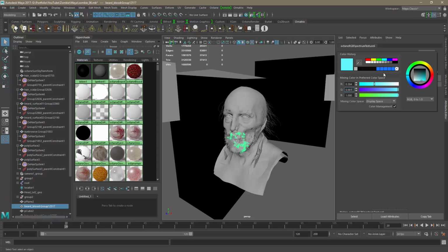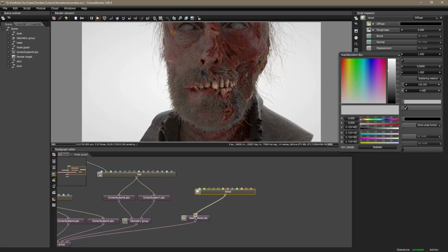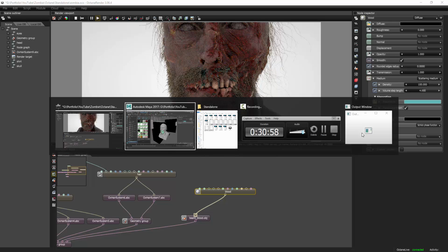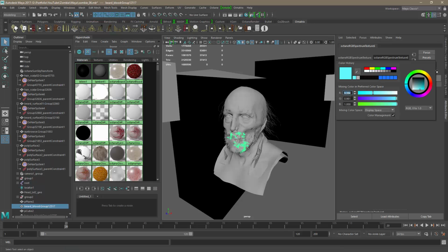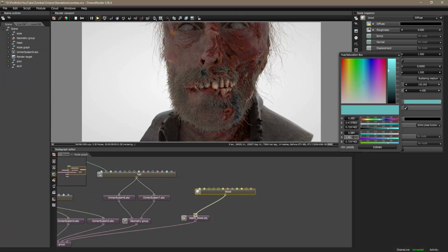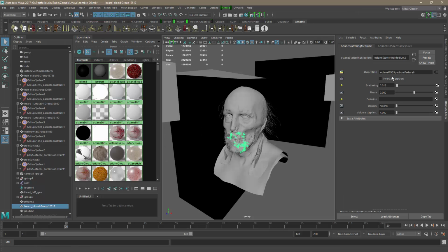This is the RGB 0 to 1, so let's copy these attributes to our absorption color. 1 and 0.981, and this is 1. Okay, uncheck invert absorption, and then the scattering is 0.015.